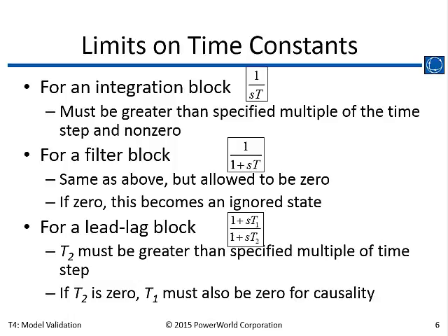There's going to be a little bit of a time delay in sensing that, and this is proportional to the time value there. If it responds instantaneously, T would go to 0. This is one where if T goes to 0, we just sort of ignore this. It just becomes input is equal to output. As that time constant gets shorter and shorter, this rise time gets closer and closer to matching that unit step.